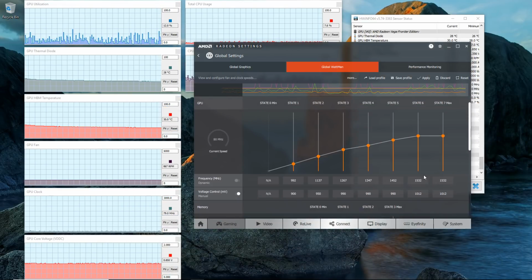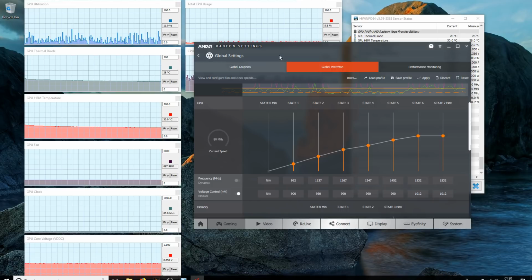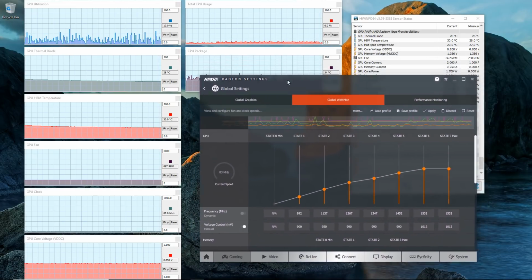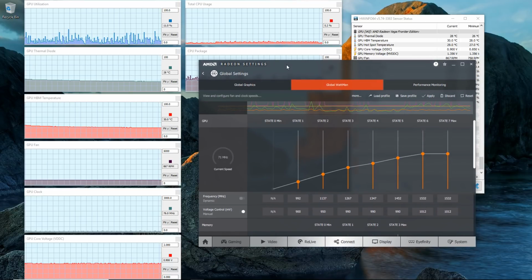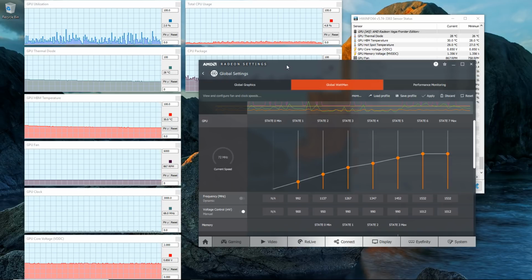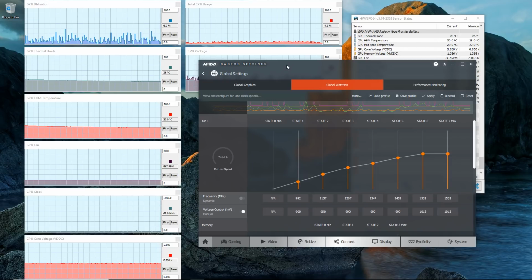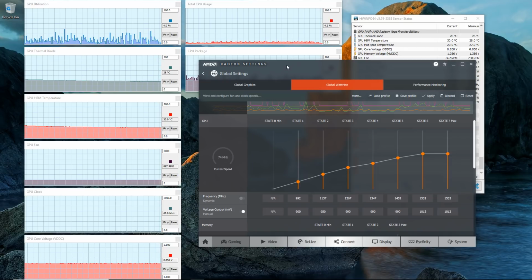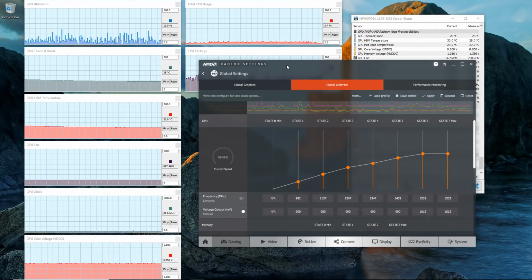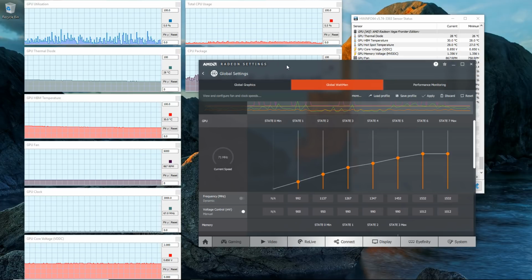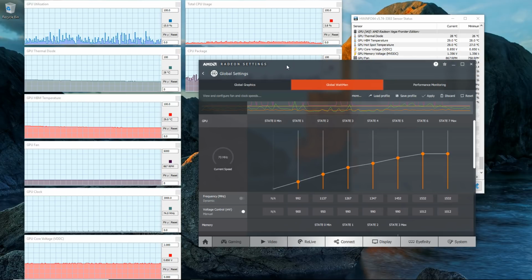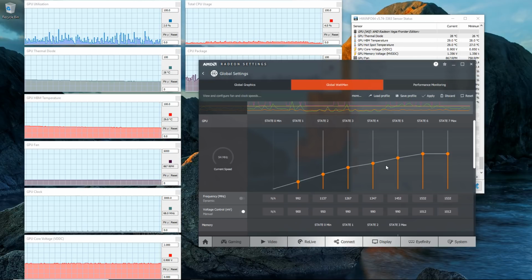You can also throw Furmark at it if you want. I don't look at Furmark as being really a valid stress test. It's really a way of trying to make your card generate as much heat as possible, but it doesn't really do a lot of independent things inside the card. It doesn't really test a lot of the GPU functionality internally. So other tests might uncover instabilities, but Furmark is good just to see if your thermals, your cooling solution, is up to standard. So hopefully this will help you out.